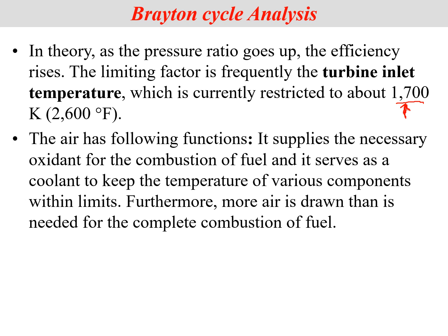Why do we have a very large amount of air? Because it is needed for the complete combustion of fuel, and secondly, it is also used as a coolant. So this is a big advantage, especially in comparison to engines as well, because as you might remember, engines are commonly kept at a very specific air fuel ratio.